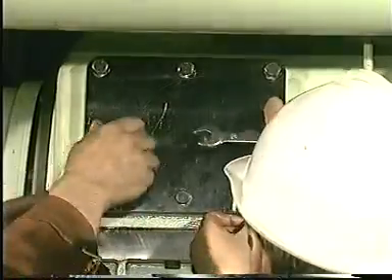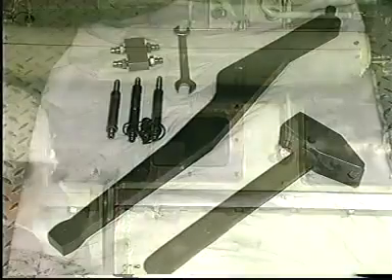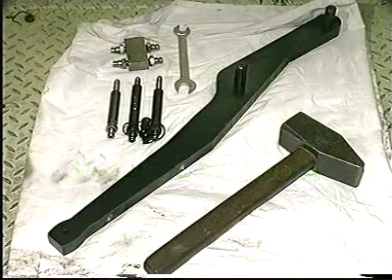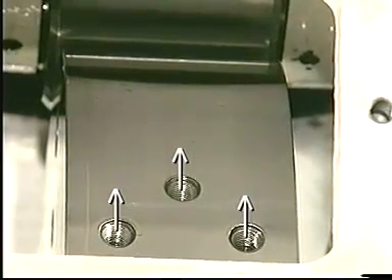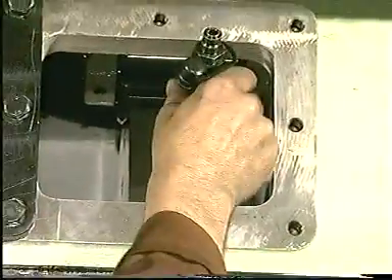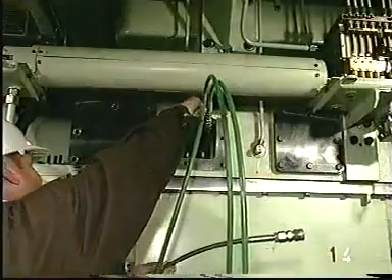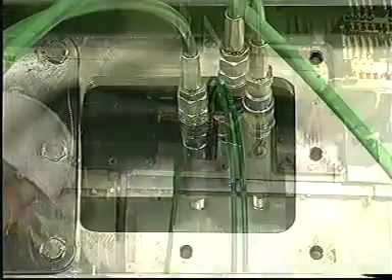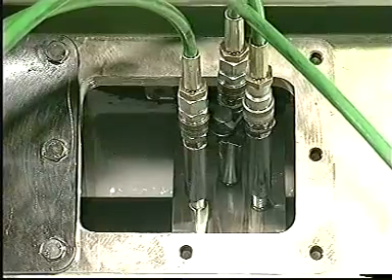If the camshaft has been dismantled or if new cams have been mounted, adjust the cams before mounting the lower part of the camshaft housing. Remove the plugs from the cam, and insert copper gaskets. Mount, but do not tighten the snap-on couplings. Connect the snap-on couplings to the high-pressure pump and vent the system. When oil without air bubbles flows from the couplings, fully tighten the couplings.